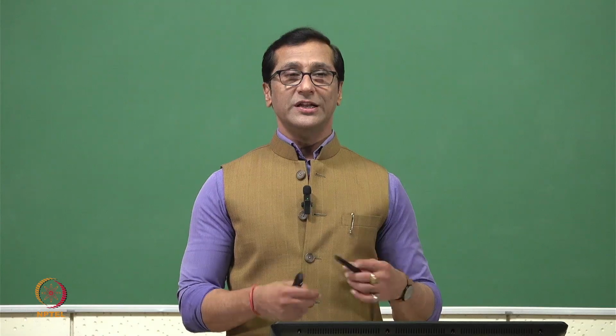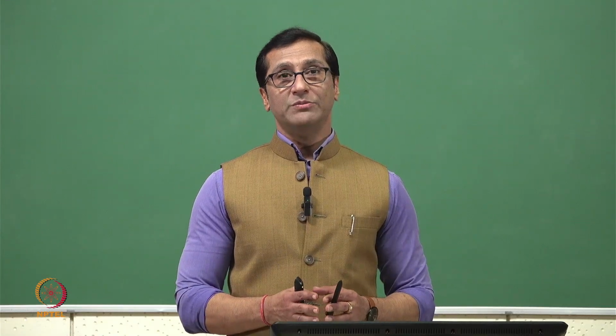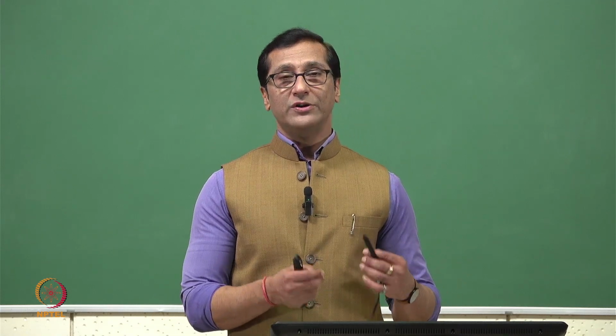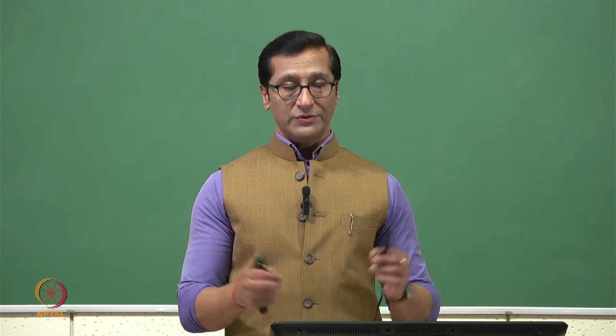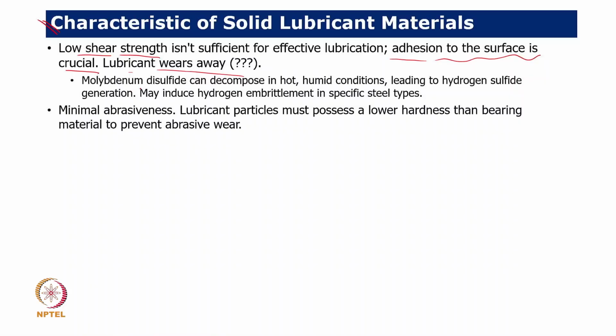That's why many times we say liquid lubricants are far better. But if conditions are not permitting, the environment is not permitting, and we use a solid lubricant, then we should evaluate what will be the life after 100 hours, what will be the life after 1500 hours. Again, we see another solid lubricant is molybdenum disulfide.